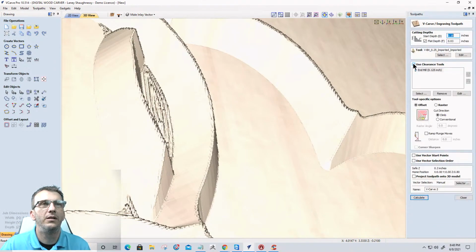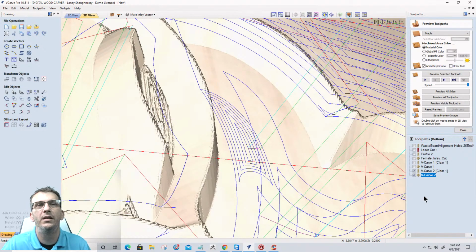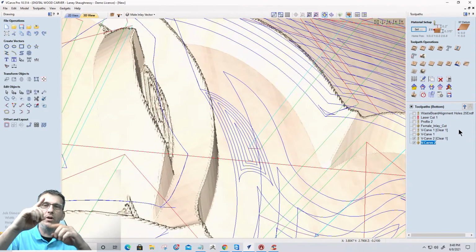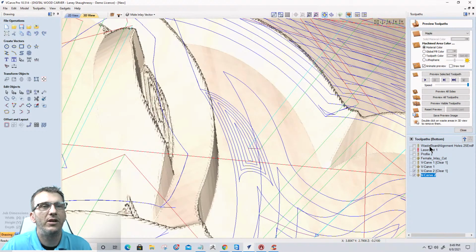Let's go here. Let's go 0.1. Doesn't matter what my start depth is, 0.1, and go 0.2 here for a total of 0.3. Now my 60-degree cutter only has a 0.21 cutter length. A 90-degree V-bit would have a longer cutting length, especially one that has maybe a 3/4 inch diameter head. But let's look, so we can really see that straight meat that I'm referring to.